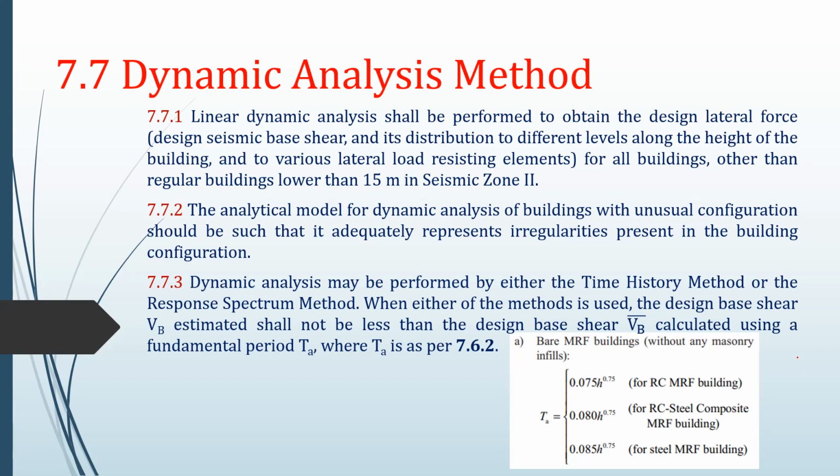While performing the equivalent static method, we calculated the time period of our structure based on formulae given in our code. And these formulae are given in clause 7.6.2. We had the formula for time period of bare moment resisting frame buildings without any masonry infills, and we also had a formula for buildings with masonry infill and for other types of structure.